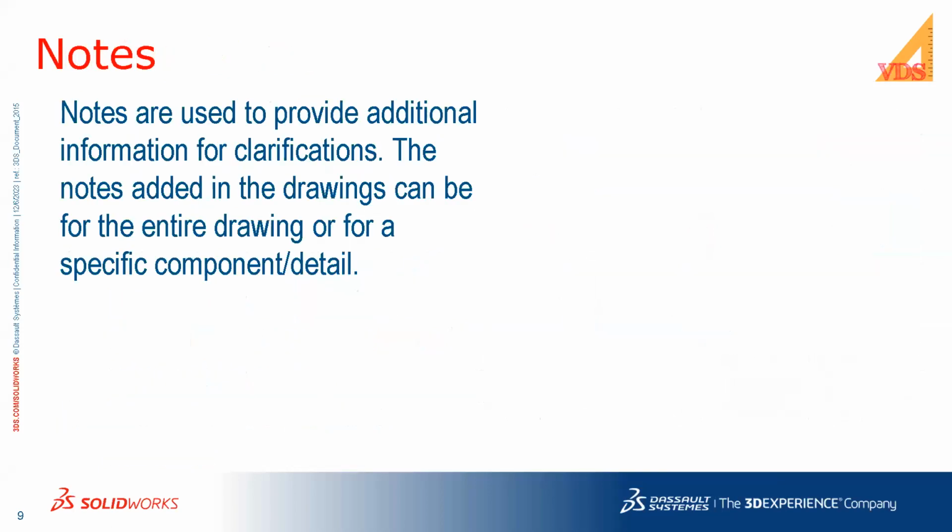Notes. Notes are very helpful in the drawing. They help us to provide general information or a particular set of information to the person reading the drawing. The notes can be related to the complete drawing, or they could be related to a particular component. They could be related to some kind of testing, or some kind of welding information, or general notes like remove all sharp edges, for example, or this particular part needs to be plated to a certain